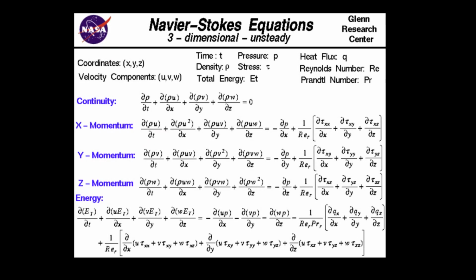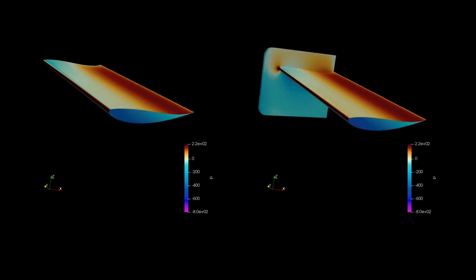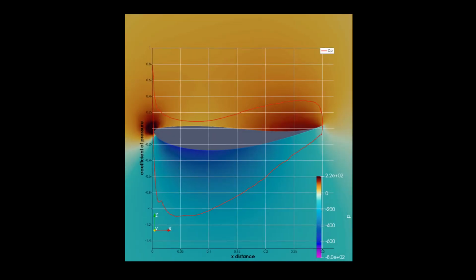Typically now, the Navier-Stokes equations are used in the finite volume method, where the total fluid domain is calculated. This is what OpenFOAM uses, and I will be using it with a chosen wing profile to demonstrate the principles of the finite wing, and how the addition of the endplates changes its performance. The chosen profile is the FX63137, which as an infinite wing had a coefficient of lift of negative 0.935 at 2 degrees angle of attack.